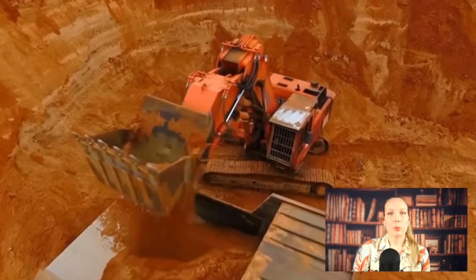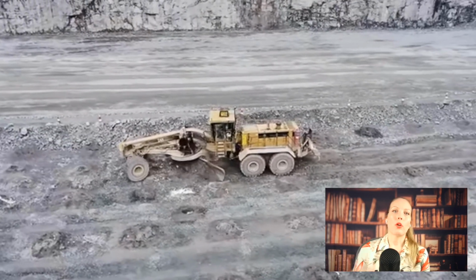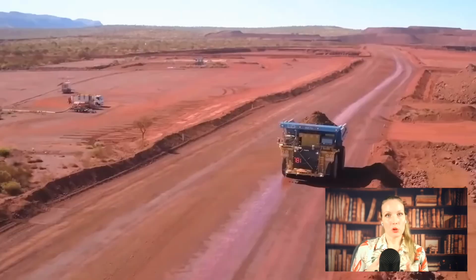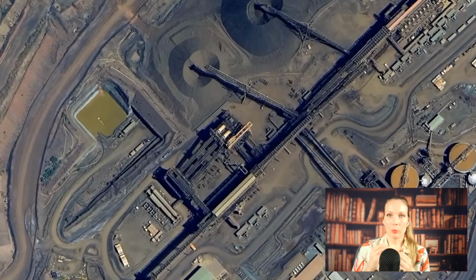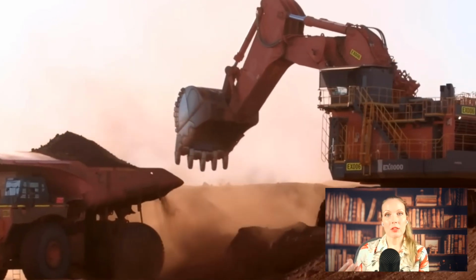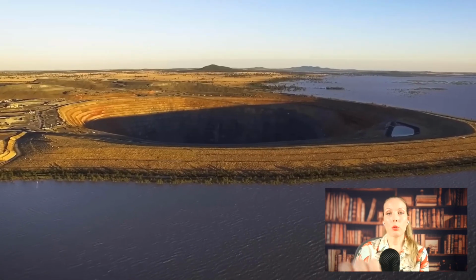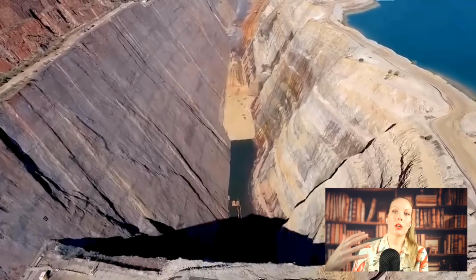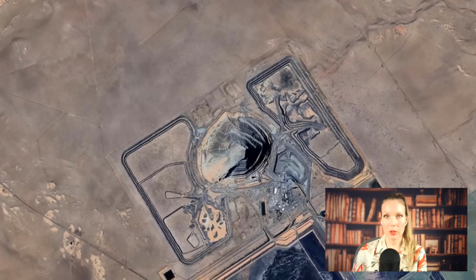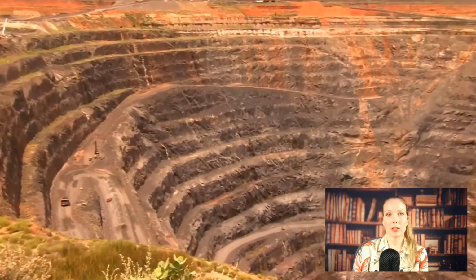So when we talk about pushbacks, there are some rules you have to follow when you're setting them up and building them out. First of all, each pushback needs to be made of unique connected blocks. This is key for planning pit roads and maintaining safe slope angles on the pit walls, and each new pushback should connect to the previous one, sharing transport links.